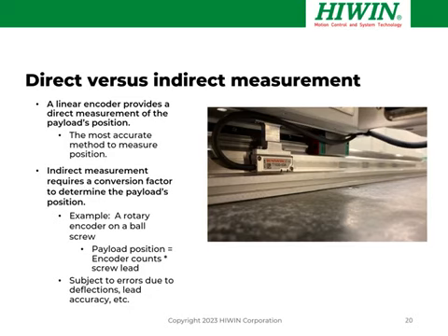wind up, etc. Another important thing about encoders generally is that they can be either incremental or absolute. Again, accuracy is not really related to whether it's an incremental or an absolute encoder. Incremental encoders are the most common. They provide relative motion from a defined starting point or a datum. Therefore, incremental encoders require some type of initialization, often referred to as homing, upon startup. Common terms you may hear when people are talking about incremental encoders are A quad B encoder or TTL or square wave. Generally, those are all referring to incremental encoders, and they're just commonplace terms that are used.